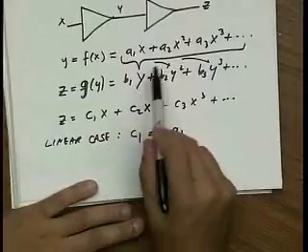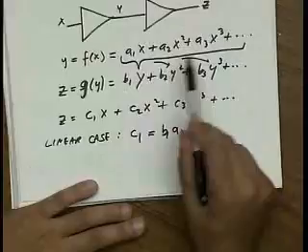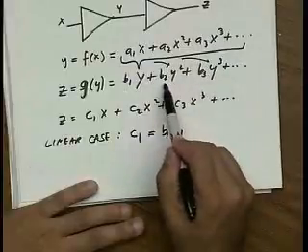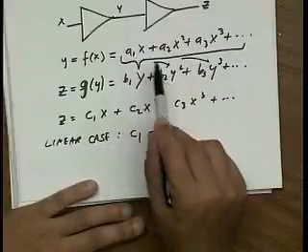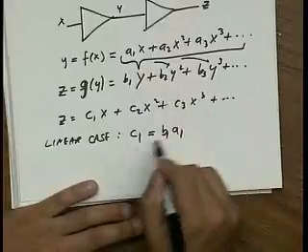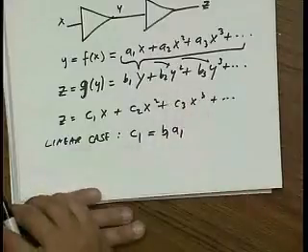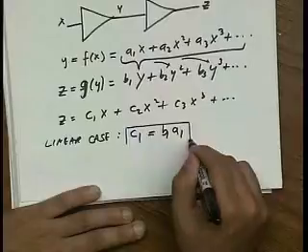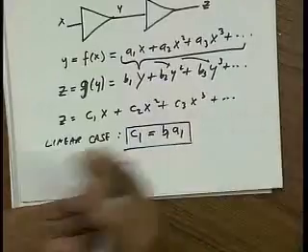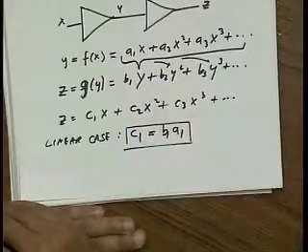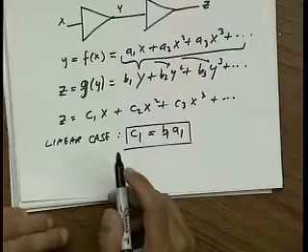And I can see that B1 multiplying any of these other terms doesn't produce linear. Likewise, here I have y squared, so even my linear term gets squared, so I'm done. These are the only linear terms. And the result is quite obvious. The overall small signal gain is just the multiplication of the individual gains, right? You didn't need to do any math to do that result.